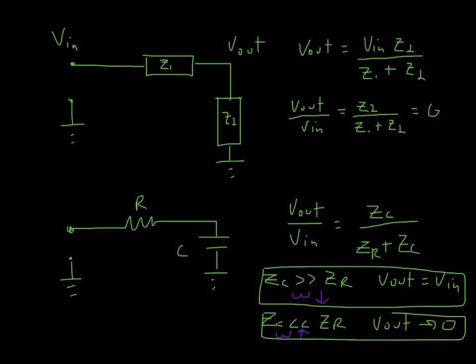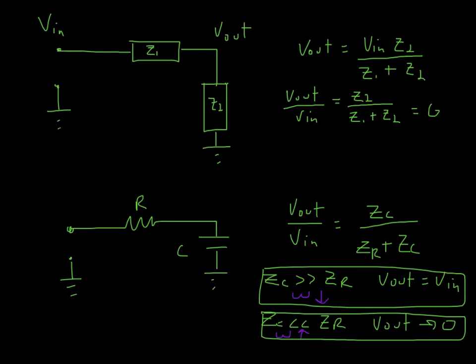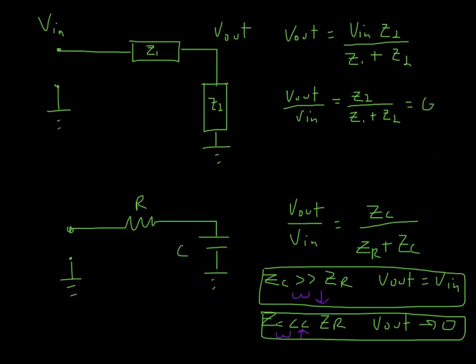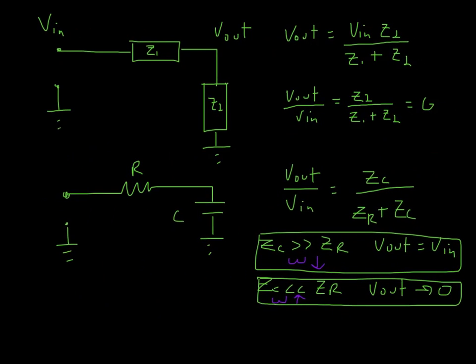So here's what we have. Now we have a circuit whose impedance changes with frequency, and in fact it's a voltage divider. And this voltage divider, we get what we put in when frequencies are low, and whoa, our gain goes way, way low when frequencies are high. And so if we were to sketch this, let me see if you can move these whole schematics up a bit. Let's move this sucker up. There we go. So if we could sketch this.